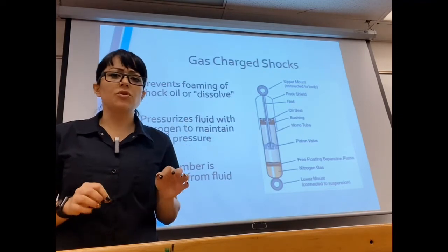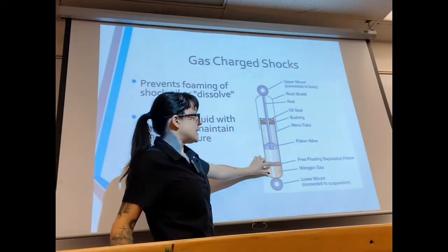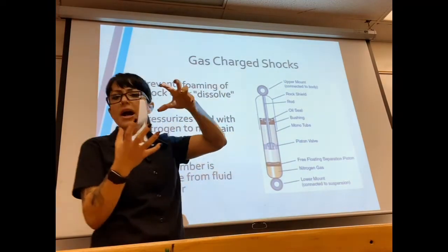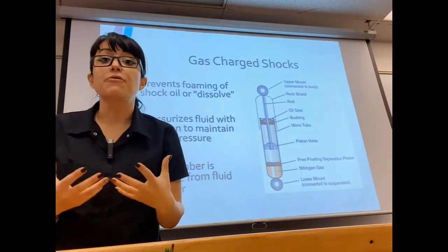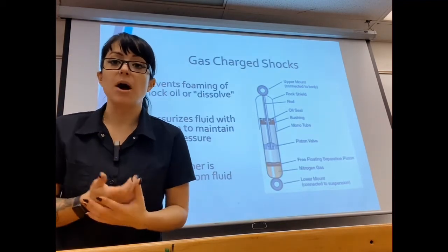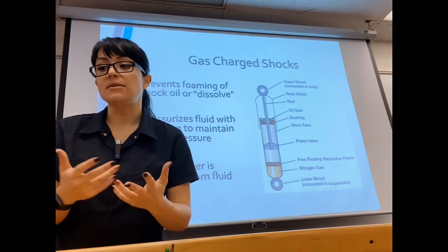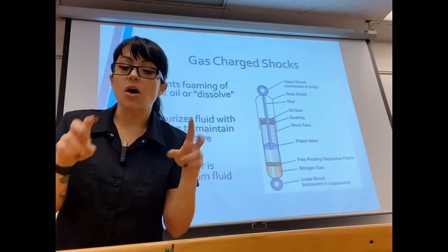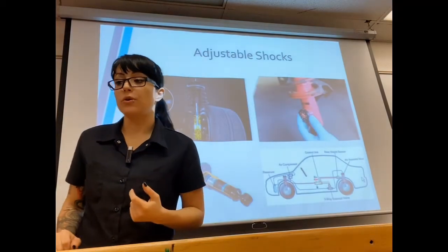So what we'll do is we'll put a gas chamber in here, usually nitrogen gas of some sort, and it's actually going to pressurize that fluid so it keeps it from foaming, and if it does build up air pockets, it can push those air pockets out. And that's really the main design of our gas charged shocks, is to limit the amount of dissolve or foaming of our oil or fluid.